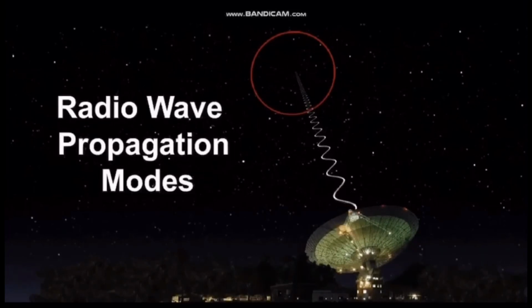The resultant radio signal may also be a combination of several signals that have traveled by different paths. These may add together or subtract from one another, and in addition to this, the signals traveling via different paths may be delayed, causing distortion of the resultant signal. It is therefore very important to know the likely radio propagation characteristics that are likely to occur.